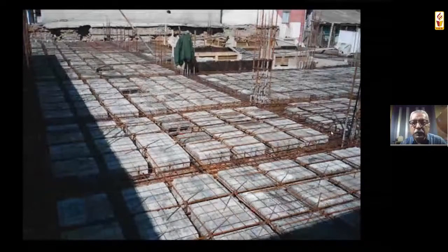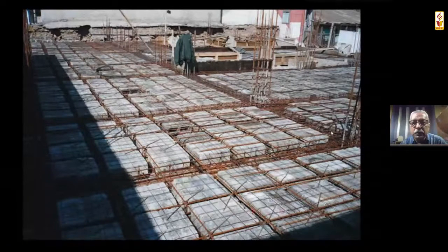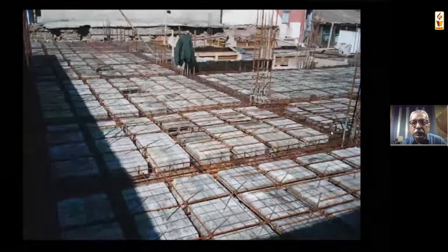So now you can see the slab is laid, and all the beams become part of that laying. Generally 300 to 400 wide beams we get according to the span and requirement. And we have done buildings up to 5 floors with this method. And sometimes if there are larger spans, you can use even concrete columns also.